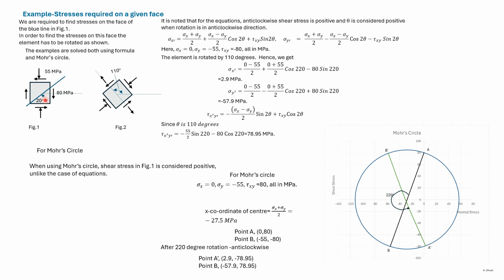On the right face, the stresses are 0 and 80. So we have plotted point A. On the top face, the stresses are minus 55 and minus 80.